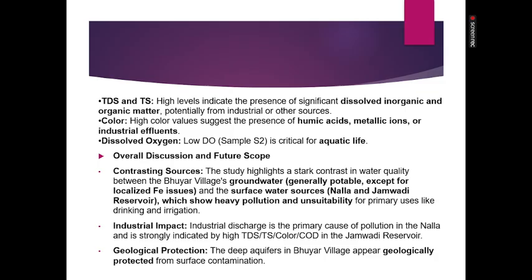The high TDS and TS levels indicate the presence of significant dissolved inorganic and organic matter, potentially from industrial or other sources. The high color value suggests the presence of humic acid, metallic ions or industrial influence. The low DO in sample S2 is critical for aquatic life.